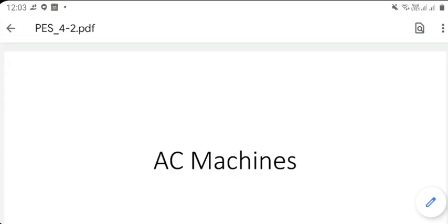So as I pointed out last time, what we do in such cases is we reverse the role of conductors and magnetic poles. We make magnetic poles rotating and make conductors stationary. That means we move all the armature circuitry, that means all the conductors, to the stator, and we put all the magnetic poles on the rotor. Faraday law doesn't care as long as you have relative motion between magnetic field and current carrying conductors. So that is the essential difference when it comes to AC generators.